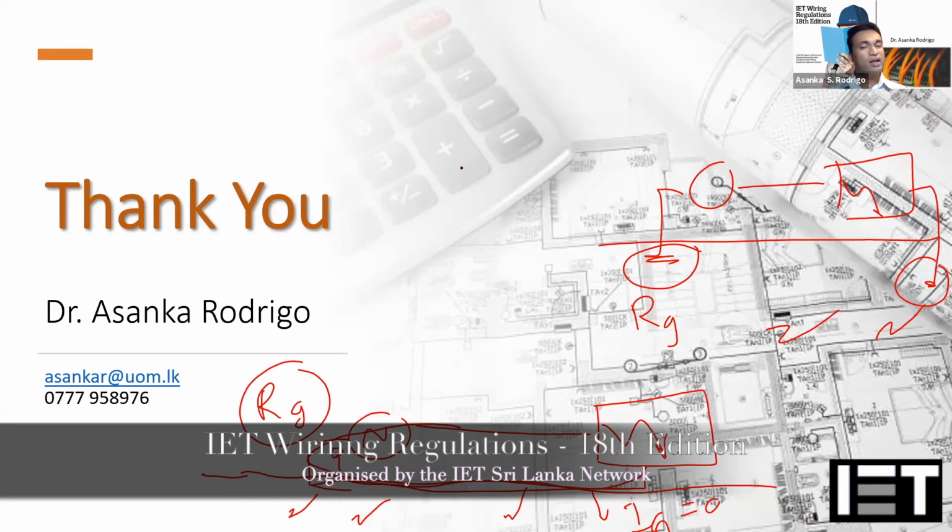fault by the circuit breaker at the meter cubicle. But in this case, you are using the armored cable, where even a single insulation failure will act as an earth fault situation, and we don't have any device to detect that earth fault.